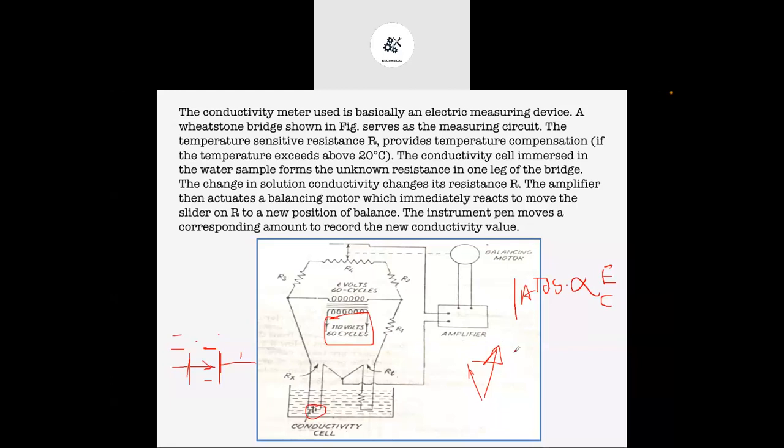If the level of this dissolved solid is more than the prescribed limit, then we have to reduce it. For that, we can carry out different methods. There are different methods to reduce the salts. We can use a chemical method, or we can use a thermodynamic method to reduce the amount of total dissolved solids. First of all, the main concern is to find out how much dissolved solid that particular water contains. After measuring that, we can carry out some processes to reduce it.